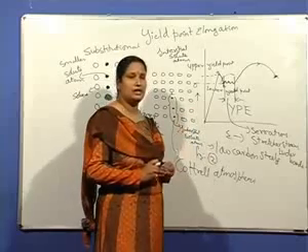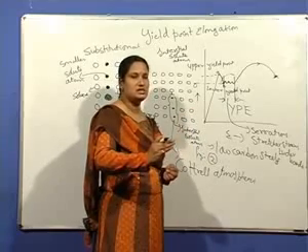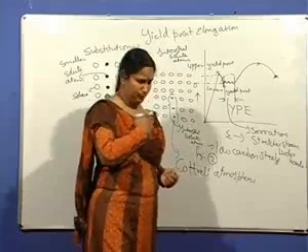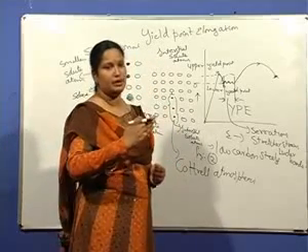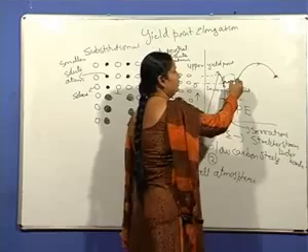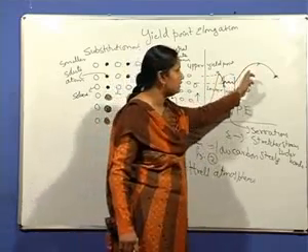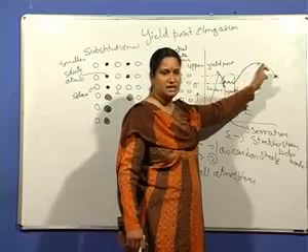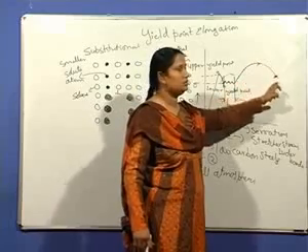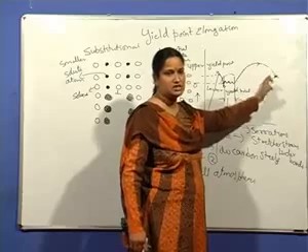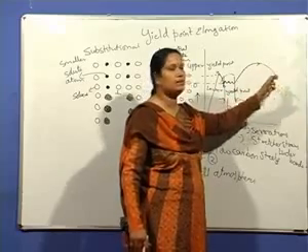which form the Cottrell atmosphere. Once the dislocations are torn away completely from these atmospheres, the curve follows the normal stress strain curve. Strain hardening is seen up to the ultimate tensile load, and then the curve drops. The stress drops, there is a fall in the curve, and the material fractures.